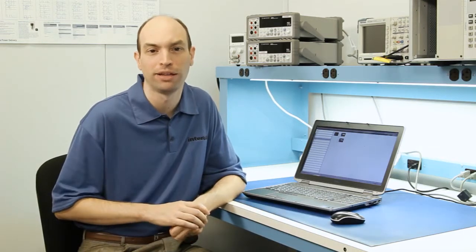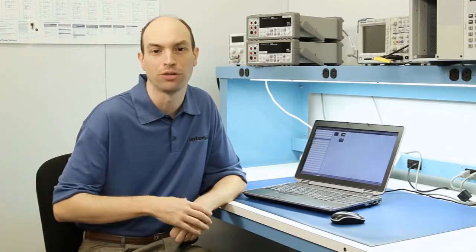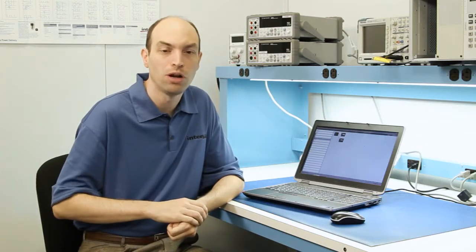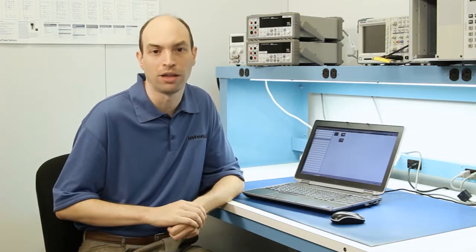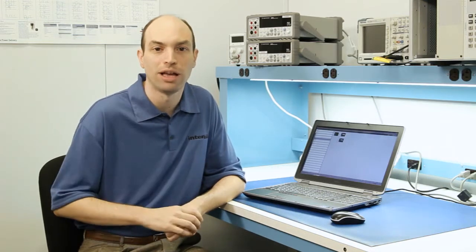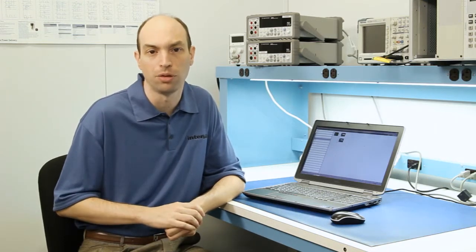To access a lot of the advanced features behind the digital power products from Intersil, you really want to have individual control and access to all the PMBus commands that set up the monitoring and configuration of those parameters. Now, with the monitoring view, you get basic information that comes back in terms of what you can set up. There is an expert mode that you can go into, which utilizes something we call a command line tool. This gives you the ability to read and write every single PMBus command to the products.